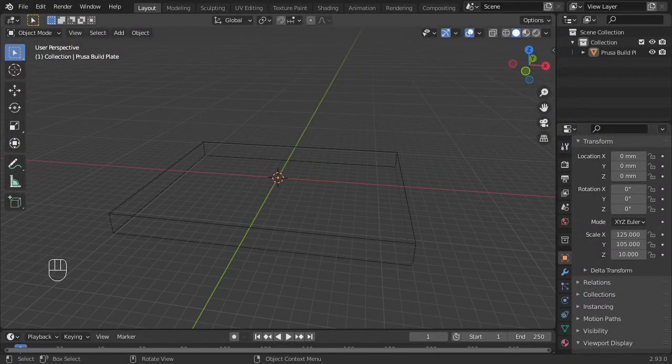Alright, this is going to be how to import map data from the OpenStreetMap project into Blender and make the necessary edits to convert it to a 3D printable STL. Prerequisites for this are setting up Blender for 3D printing. I used the 3D Printing Professor's Blender setup tutorial, and then also installing the blender-osm plugin.